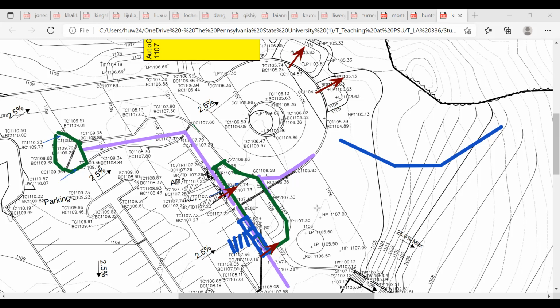Did I make any mistake in the process here? Oh, I don't know. Yeah, that's an interesting idea that I'll have to look into and do some calculations and see if that area can handle the runoff. It should be able to, because it should be roughly about 1/12 of the entire drainage area. And because you have a green over here already, right?